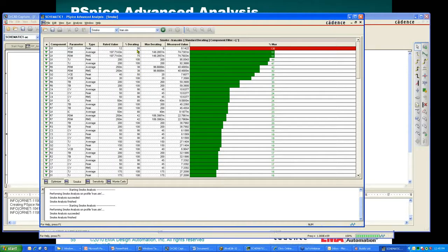So I'm only driving the VCE parameter, for instance, at 50%, which means that for a maximum peak rated value, it's going to flag an error if anything is over 6 volts. So in this case, my measured value for the simulation is 8.1. That is indeed over 6, so it's telling me I'm exceeding that particular parameter by 136% there. So it gives you an idea of how hard you're driving these parts, and you can even back off of certain absolute maximum ratings if you want to design in a margin of safety there for things.